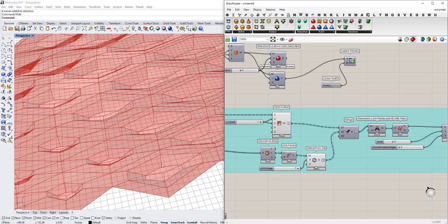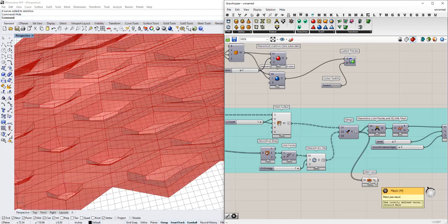That means that the vertice list is only drawing the mesh faces where those vertices are, and if you happen to have two of those vertices overlapping, it doesn't naturally combine them. So tools like this, you have mesh join is another one that will join them together. This does not weld the meshes, it just joins them together into one mesh, which is something we can do, and you'll see that it updates into an invalid mesh, which is unfortunate.